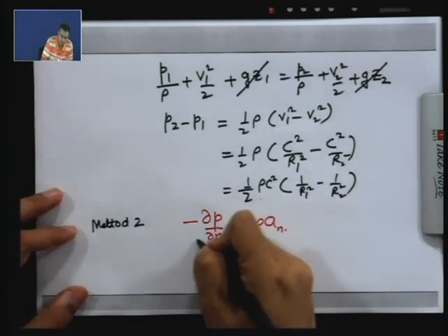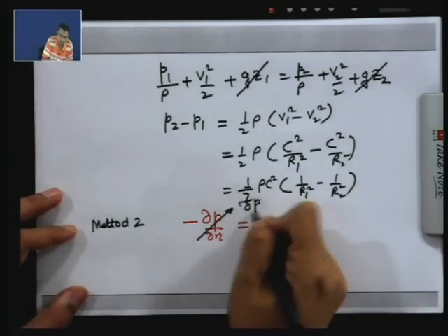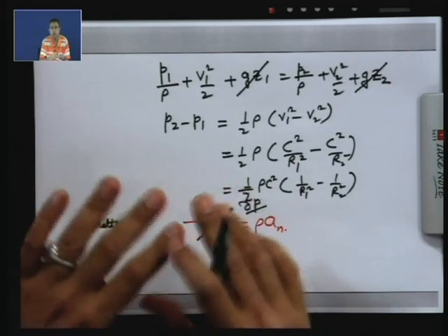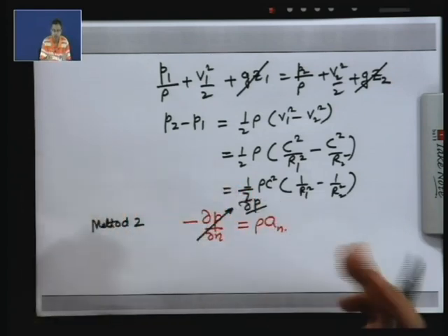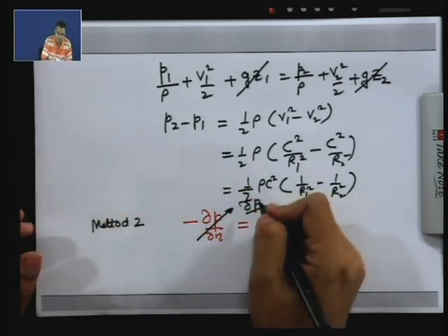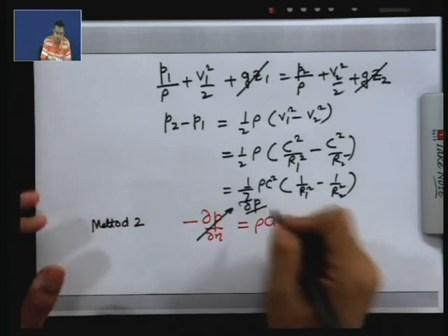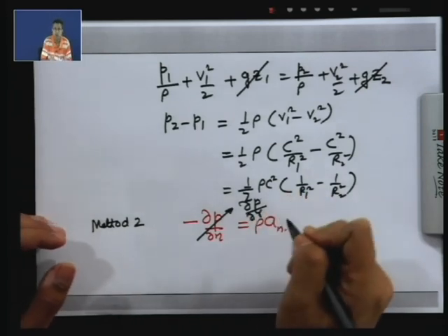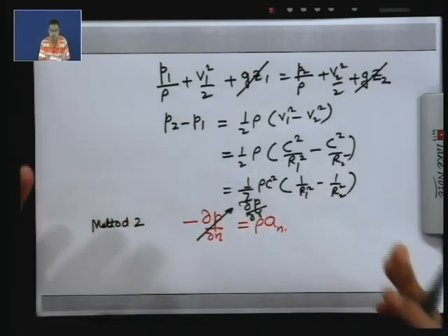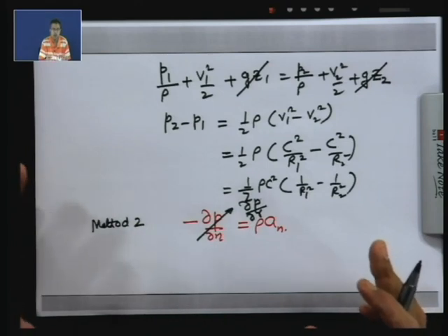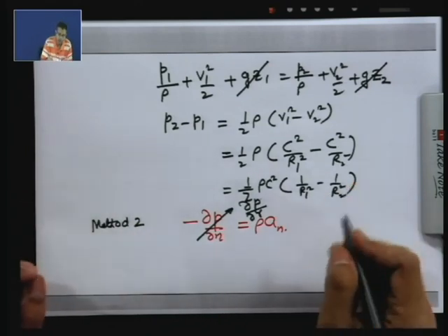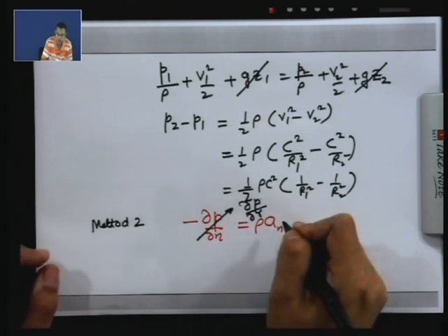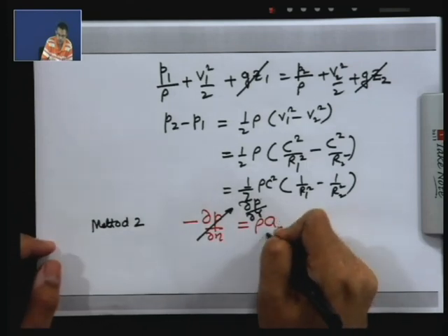In place of del P del N we can write del P del R for a system where the radial coordinate is the same as the cross streamwise coordinate. Because we consider that the bend is a part of a circle, the cross streamwise coordinate is the same as the radial coordinate. So in place of del P del N we write del P del R, and A